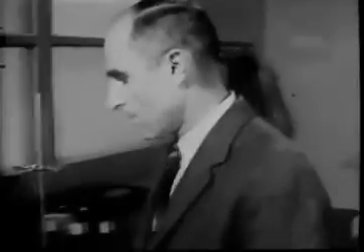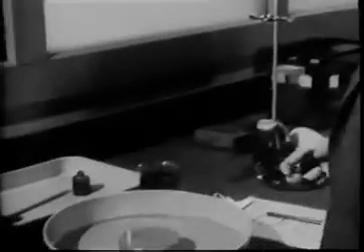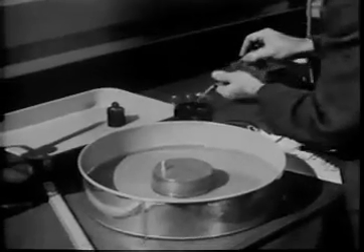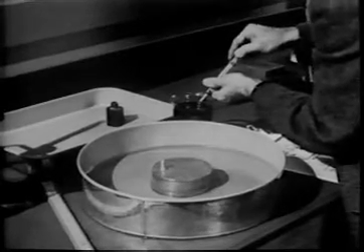There is one very important additional fact you need to know about viscosity, and that is that the fluid immediately adjacent to a solid surface cannot slip relative to the surface. What is more, the particular material of the surface, wood, metal, glass, plastic, cannot in any way alter the viscous behavior of the fluid. This liquid is glycerin. I am loading the marking pen with colored glycerin.